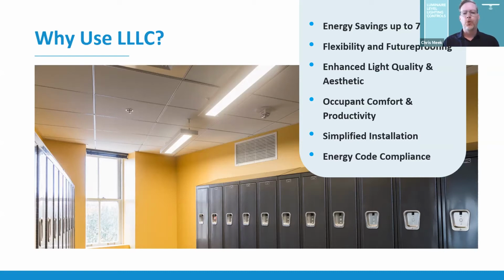We also see improved quality of light, where the controls response of the light fixture is more closely aligned with the location of the luminaire, and the potential for improved occupant control, really delivering a better user experience and improved productivity and comfort for users. We see improved simplicity of installation due to the wireless network capability and standard settings coming right out of the box, essentially pre-commissioned to standard user expectations. And then LLLCs inherently meet the most stringent energy codes via onboard sensing and occupancy and daylighting control for each fixture. So there are a lot of reasons why we would want to use luminaire level lighting controls in our buildings and projects.